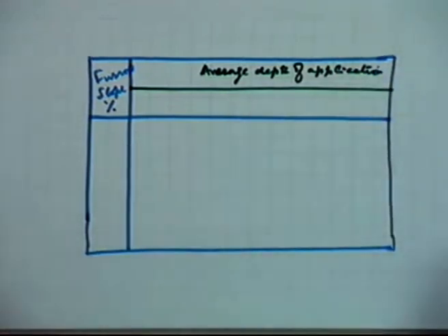Now the irrigation application requirement is not a fixed requirement. It might be varying. It is dependent on the management and the farmer, at what time they want to irrigate, and accordingly the amount of water which has to be applied as irrigation water. The depth can vary. It is also a function of different types of schemes, whether it is a rotational irrigation scheme or an on-demand irrigation scheme.